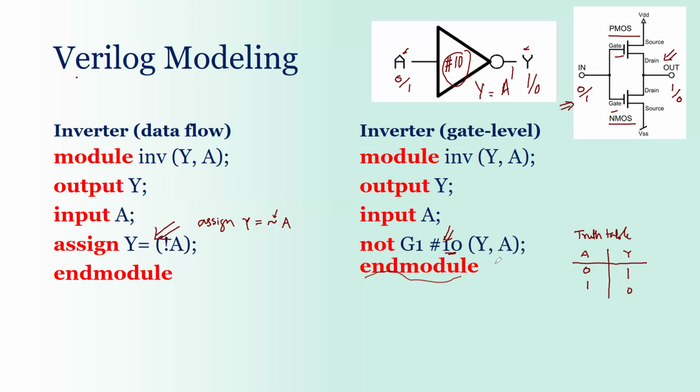Then obviously you have the end module. Once you have this code, you can confirm whether the syntax is right or wrong by copy pasting or directly writing this code in the Verilog compiler. There are a lot of online compilers available, cloud-based, or you can download and install one on your computer, open that compiler, and just start writing the code in the compiler itself and then execute. So if the syntax is correct in both of these gates, you will run into zero errors. And that's what you want.